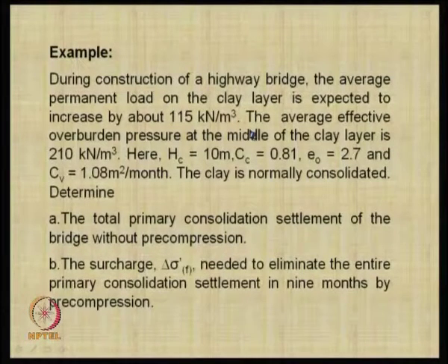So, at some point, say for example, you have 10 meters of the embankment, you will be able to calculate stresses at every 1 meter level. What is the extra stress because of the embankment construction of 5 meters? It could be very high, but as you go down, the additional stress that you can expect from the load is less. That is what we sometimes say, twice the breadth, like the pressure bulb.